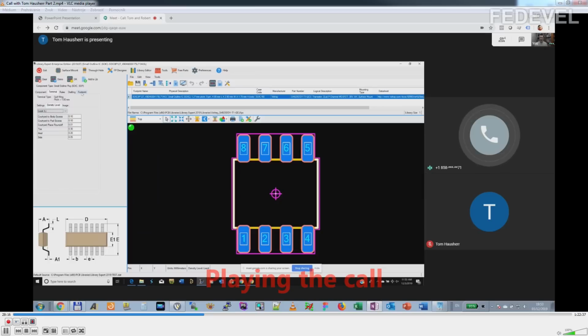Okay. So Dieter Bergman went over to Japan and found this out, and he came back and gave a webcast and said, guess what? We need to remove the most density level from IPC 7351, from the standard, because the Japanese are telling me that the most density level doesn't do anything to hold the parts securely to the board over nominal. Nominal is just as good as most. But Karen McConnell, the chairperson, jumped in and said, well, wait a minute, Dieter, we just can't remove the most density level. It's got to have some use.